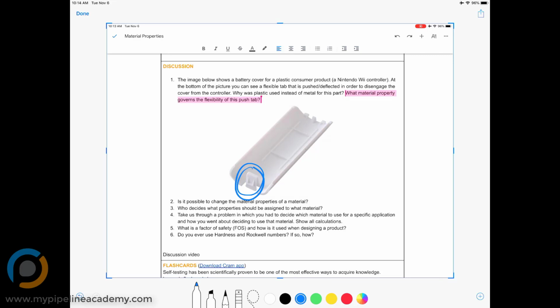For the amount of stress that we're calculating for, when a person puts their finger in there and they put a certain amount of pressure, we're calculating for that pressure. And we're choosing a material that it's going to come back to its original form after a certain amount of stress is put on it. So we have to calculate how much stress we're going to put in it, right? That's right. Yeah. Ballpark, at least.